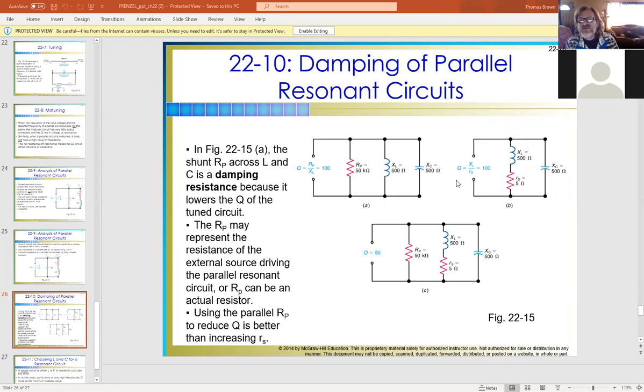So really, when you come down to it, in a realistic world, ideally this bottom circuit C here would be what you're dealing with. And look at our difference. We've gone from this to this, and now our best circuit would be this one here. We've gone through and put a 50K in parallel with these two other components to help balance the circuit, or damping, if you will.